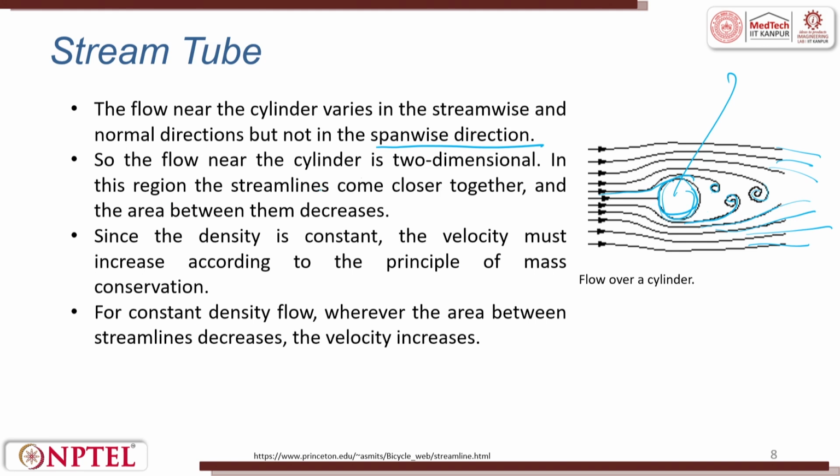In this region, the streamlines come closer together and the area between them decreases. Since the density of the water which is flowing is constant, the velocity must increase according to the principle of conservation of mass. The velocity increases according to the mass conservation.